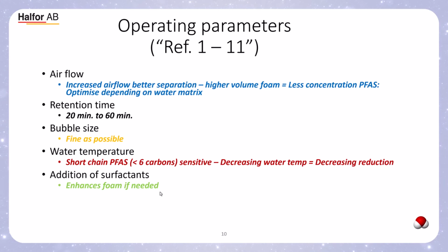So increased airflow needs to be matched against the waste stream and the concentration of PFAS. And pilot trial, lab trial to see what is the optimum airflow for your water or water matrix. The retention time in a plant foam fractionator would probably range between 20 to 60 minutes. If I were to set up a pilot trial, I would probably go for looking at 30 minutes and then maybe 60 minutes to compare.